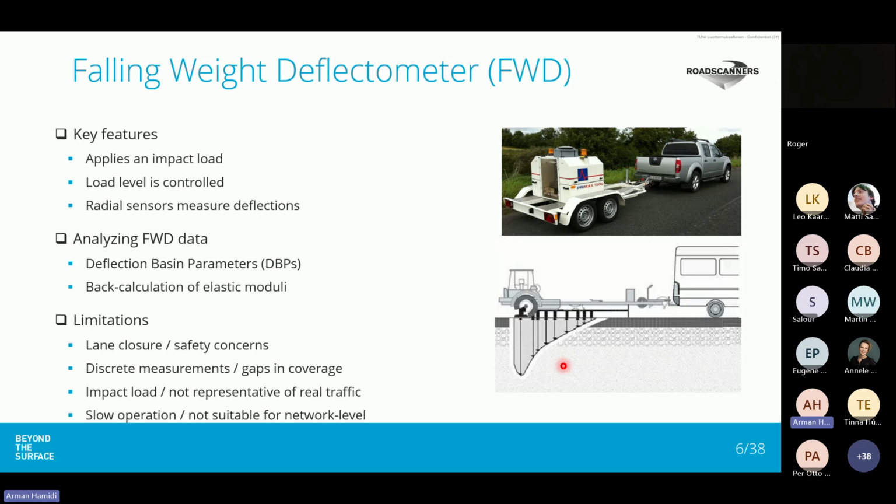In this regard, we can remember again that in the flexural bending test, we have a known load, and we also have dimensions of the material, that is pavement layer thicknesses here. So we can determine these using GPR, and we have a response, which is not a single value, more complicated, but by relating the load, dimensions, and the response using a software tool, we can estimate the elastic moduli of pavement layers. Although FWD can provide pretty accurate measurements, it has several limitations.